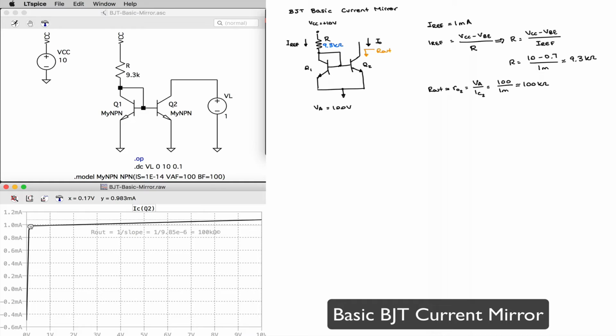it depends on the specification, it depends how accurate you want your current source to be, but you could measure it, for example, when it drops by 5% of the nominal value. And so you will see that it's actually something very close to zero. It's going to be probably 0.3 or around that, around the saturation voltage of the transistor.